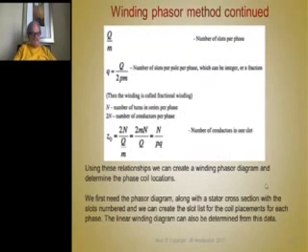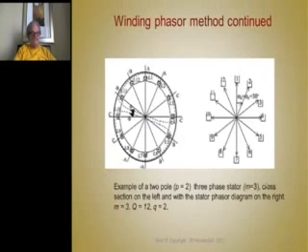So what do we need to do? Well, first we got to have a phasor diagram along with a stator cross section with the slots numbered so that we can find out where the coils go. And then we can create a slot list for the coil placements for each phase. The linear winding diagram, or the pattern, if you lay out the slots in linear fashion, as you've seen on a lot of documentation, then you could find out where all the coils go from this data.